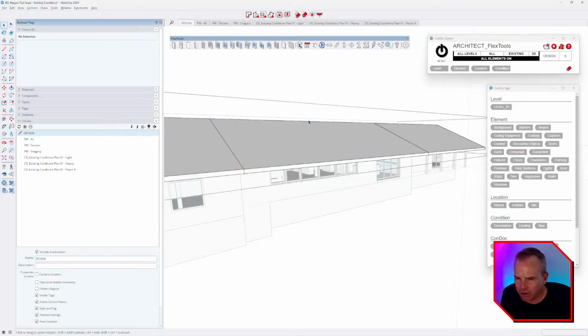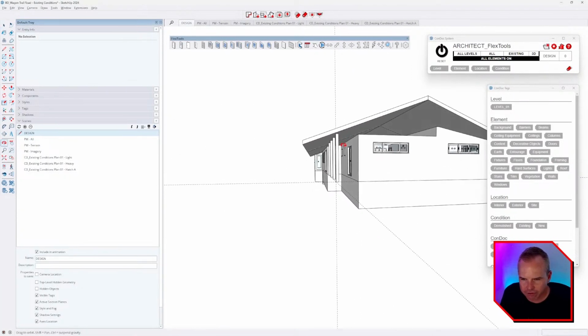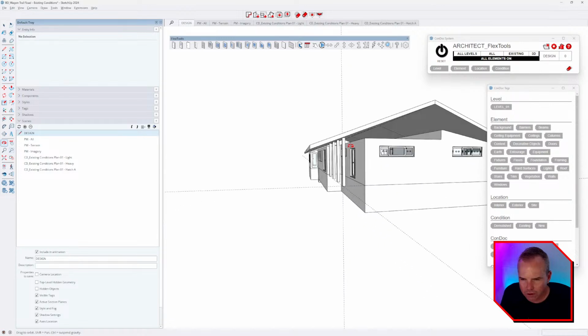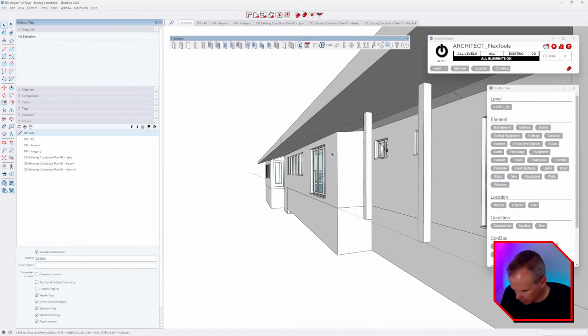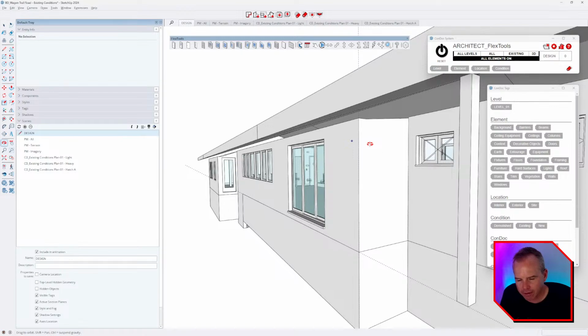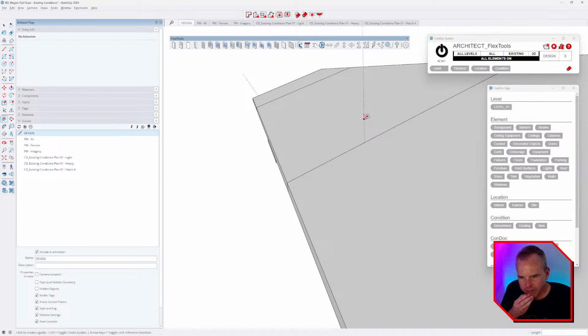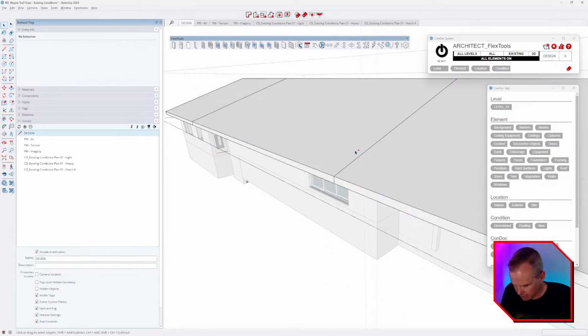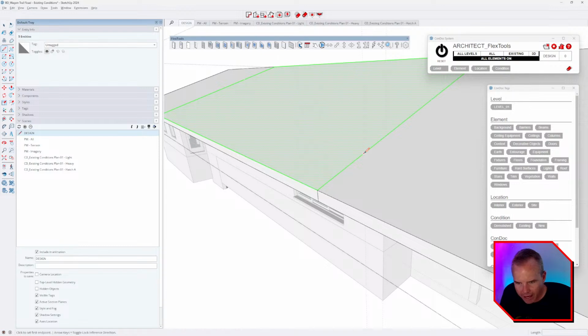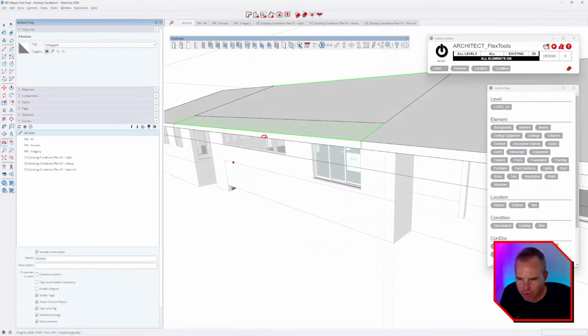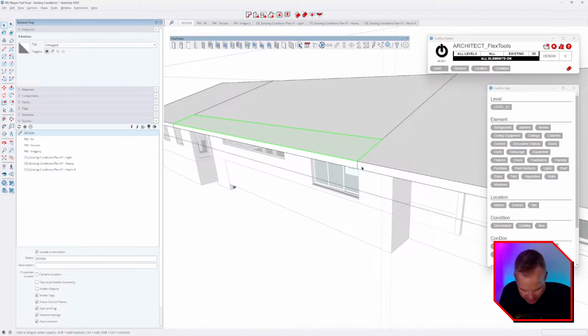So maybe our standard overhang, it'd be good to define the rules. Well, let's just stick with what we're doing here. We're going to plot this point up to there. And then from this face, we're going to come out on the green by 2 feet. And so then you can drill in here, and with your line tool, you can say, yeah, that we can get rid of. And I tend to just group it and delete it. Or actually, I'm going to undo that and undo that.